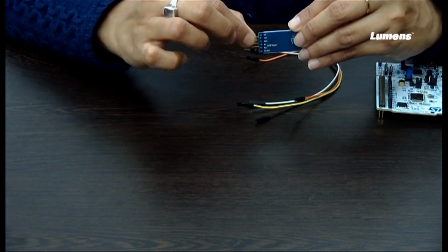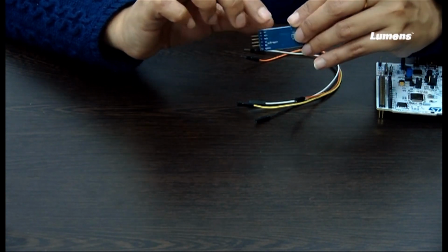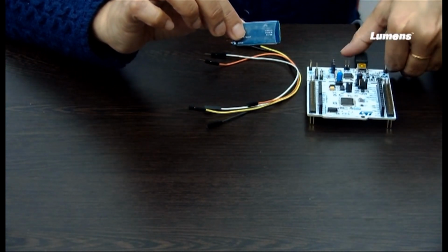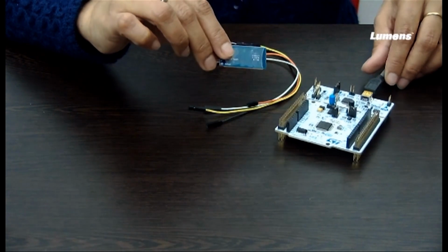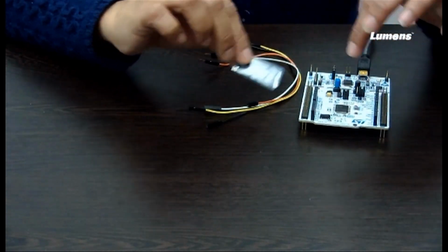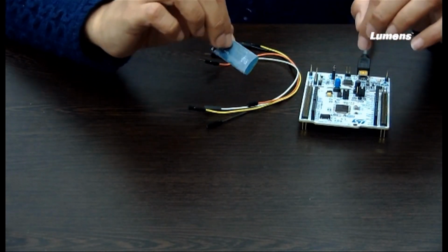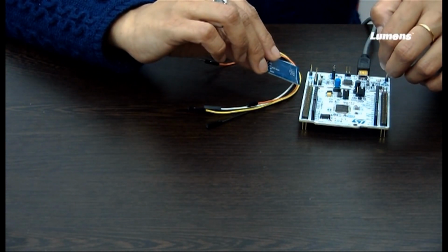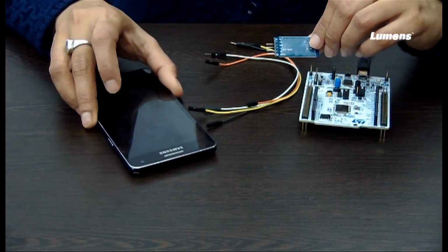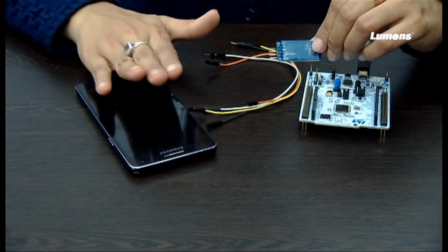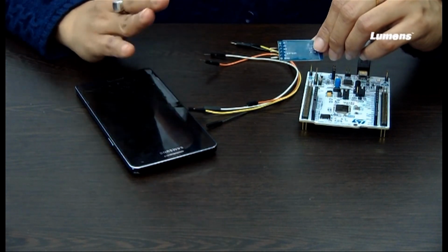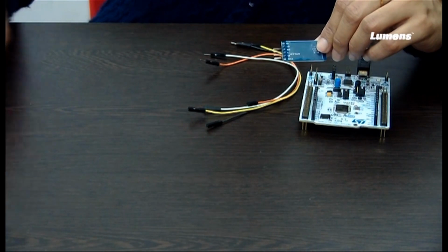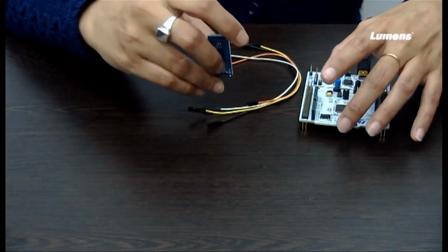So I will be connecting this with the ground, VCC and TX, RX pins of this STM microcontroller with which we were working. First we will just connect these two and we will send data from this microcontroller to my device. Okay. For doing this you also need one more thing: you have to install a Bluetooth terminal. I am coming to that a little later. First, let me show the connection here that we have to make.